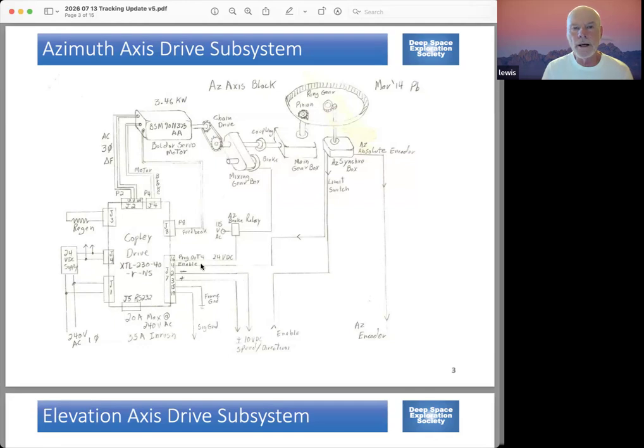the rate up to the commanded value. It doesn't just immediately slam it. And actually, that ramping factor is a tuning factor in it. And the same thing is if you command it to a slower rate, it'll ramp it down to that rate. And so that helps in terms of jerking the mount around.